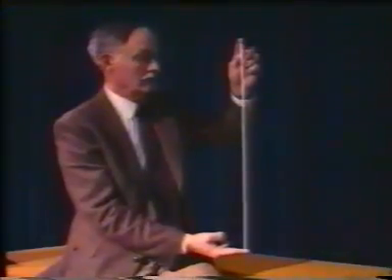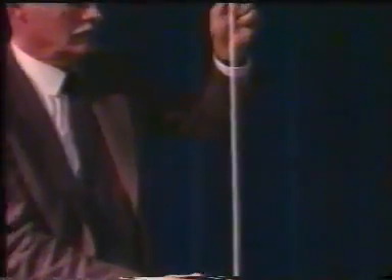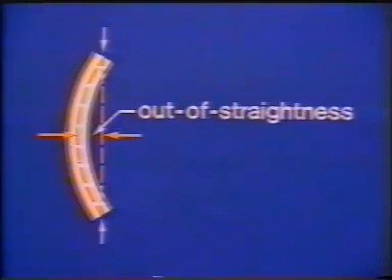If the column is slender, with a relatively high value of slenderness, the column will deform out of its line as the load is increased. This deflection starts in real structures by the presence of an initial distortion or out of straightness in the column caused by the rolling and fabrication processes. As the load increases, the lateral deflection increases non-linearly.